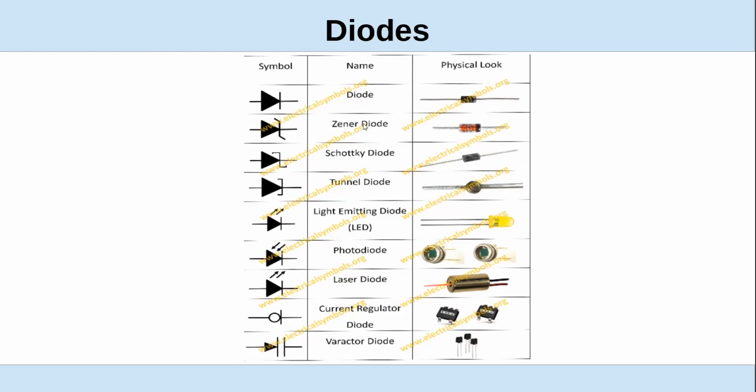By the way they make the material, they could control that breakdown voltage, or the Zener effect. So they can do these at a whole range of voltages, 5, 10, 12, pretty much whatever you want, and use them as a simple voltage regulator with a resistor.